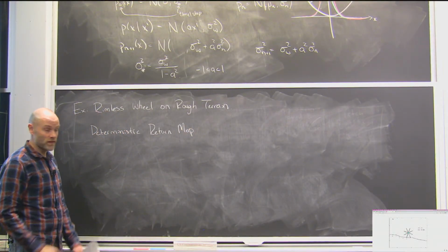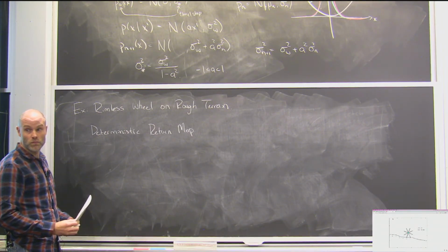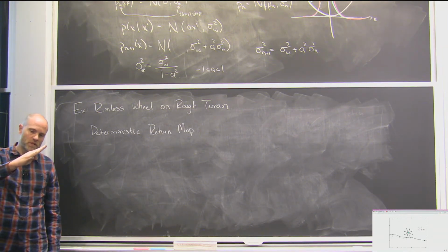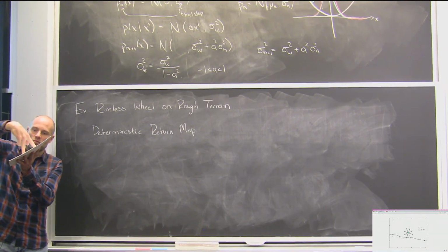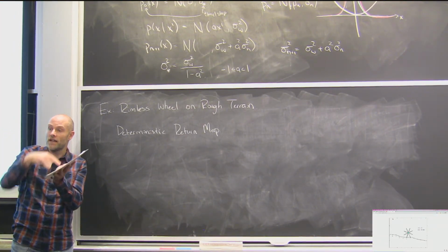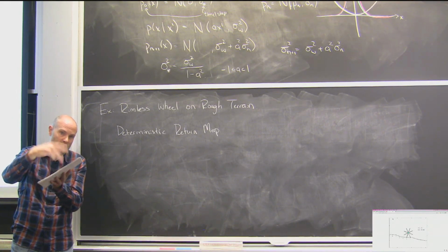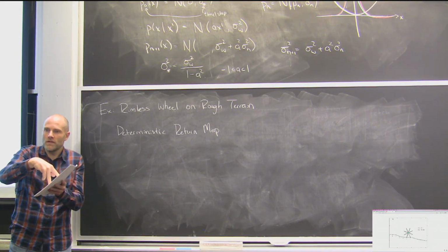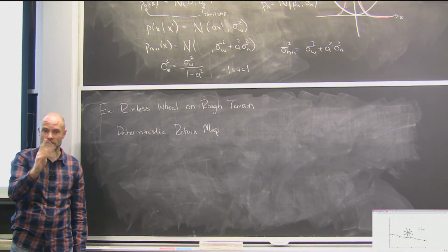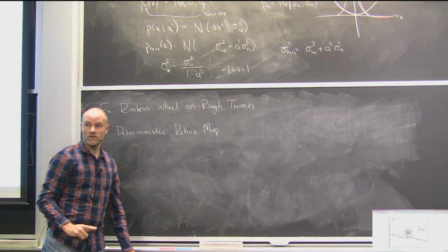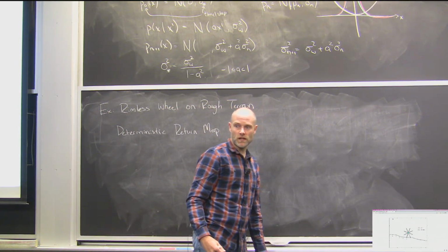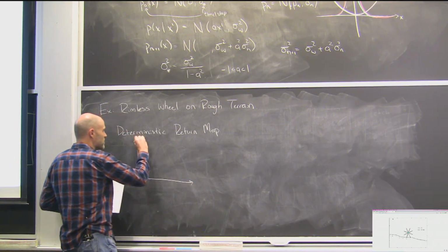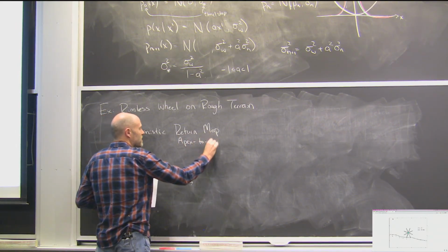So let's remember that for the deterministic rimless wheel, we could compute the Poincare map. When I did it before, and my favorite version of it for the deterministic thing, I put the coordinate system, the return map, starting when the foot's on the ground and ending after the next impact when the foot's on the ground. That's the simplest math, I guess, and the cleanest presentation of it. But it doesn't work if your ground's going like this. That's like a moving coordinate system. So no big deal. We'll just take a different slice, a different Poincare map. We'll do it at the apex. So it's when the stance leg is vertical until the next time the stance leg is vertical. Okay? It's going to make the picture look slightly different, but the ideas are the same. So this is the apex to apex map.